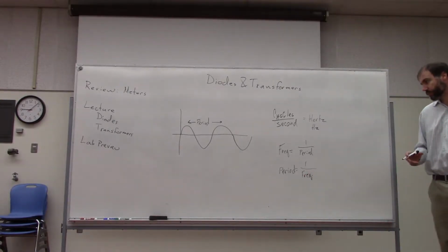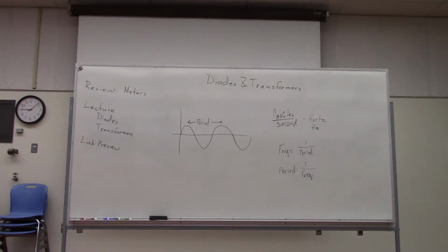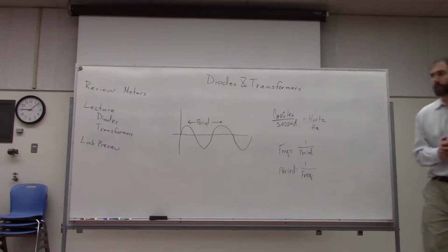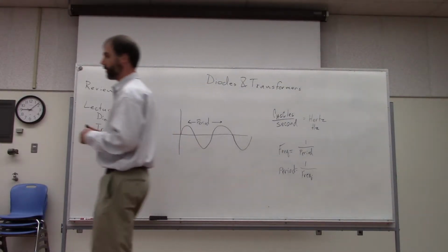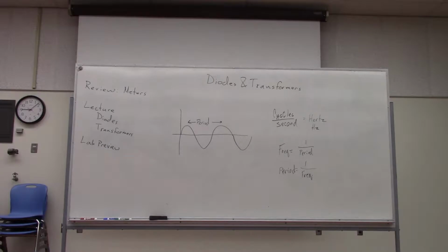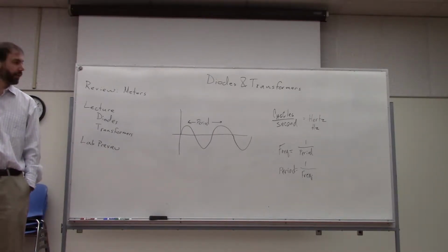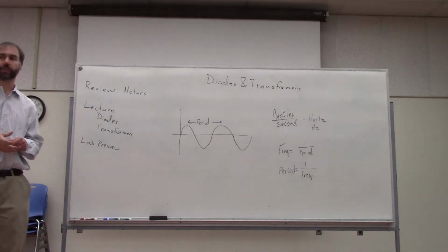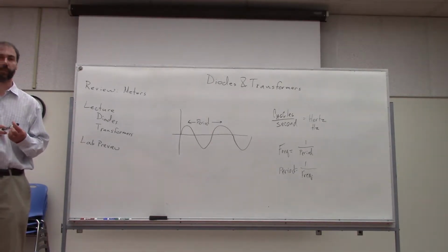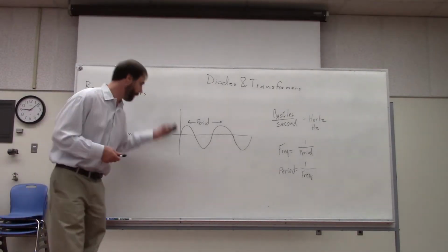So that's a little bit about what frequency actually is. We said that we could use the meter to measure frequency, right? There's a frequency position, and you just move the dial over into the position where it says Hz for hertz, and then the meter will measure frequency for you. Okay. Any questions about frequency? Okay. Then we talked briefly about capacitance, right?